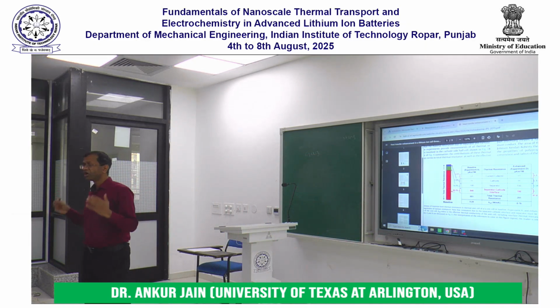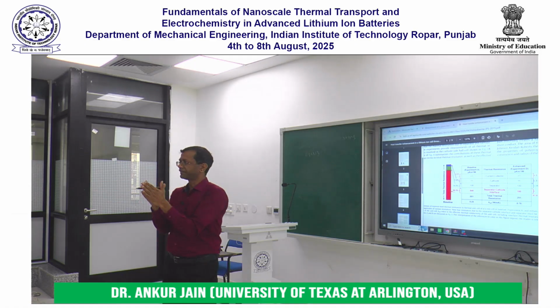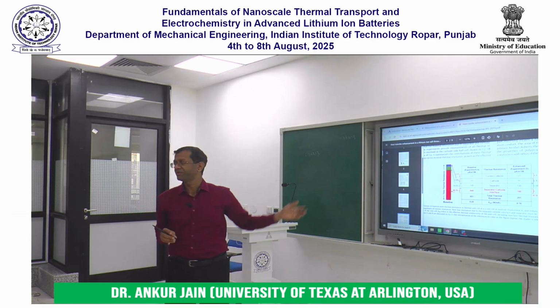And this is not uncommon. This is not the first time people saw interfacial dominance like this. In microsystems, when materials are very small, interfacial dominance is quite common, because imagine I have a material that is becoming smaller and smaller and smaller. Once it becomes small enough, then the heat can pass through it very quickly. But the interface continues to offer a problem. Here, the materials themselves are conducting enough, but the interfaces are very poor. And there are reasons behind that.